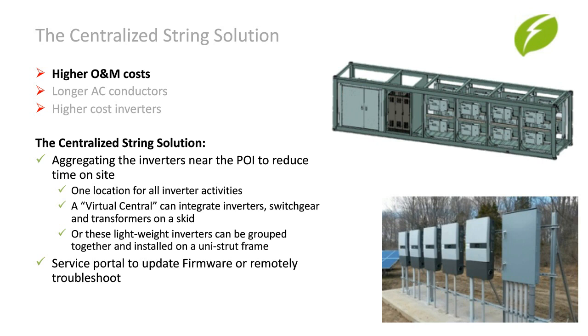This certainly will raise the cost of the system as much as 2 to 2.5 cents per watt. But what we gain from this is an easier O&M plan on potentially very large sites of 20, 50, 100 megawatts and more. And with the potential of having the AC wire from the inverters to the switchgear and/or the transformer pre-wired prior to being dropped on site, we are saving installation later as well.